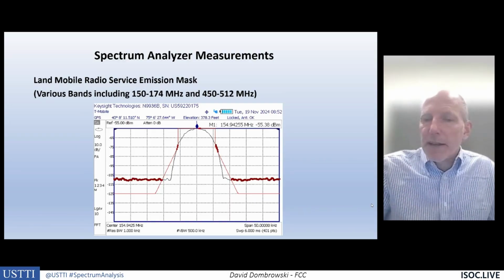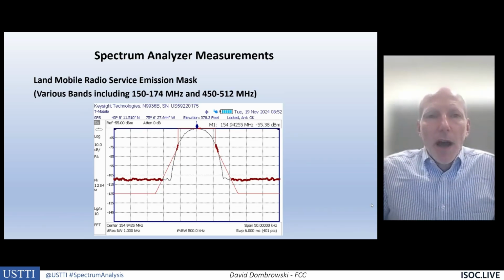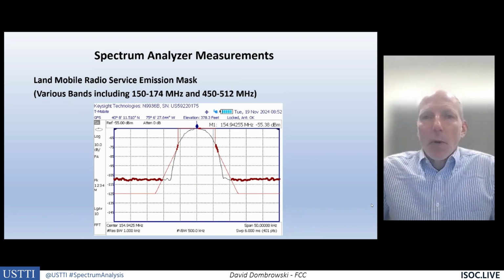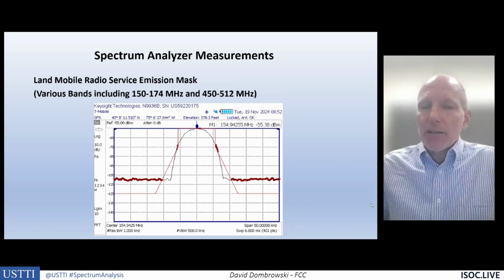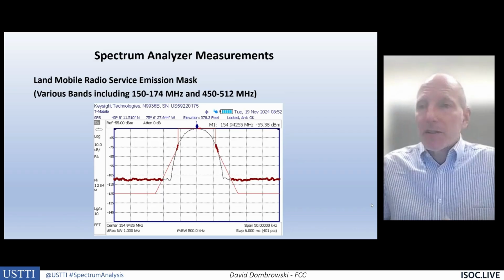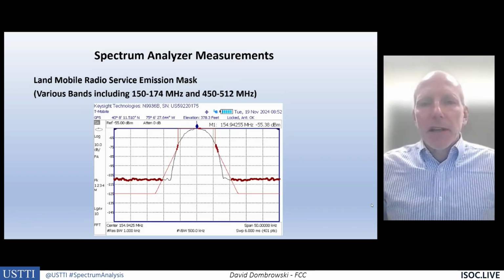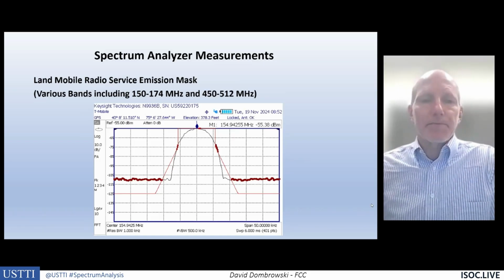And if you attended the interference presentation earlier this week, Shannon was talking a lot about interference, co-channel, and adjacent channel. And spurious emissions are very important. We have to attenuate those because those are the ones that we always find. The transmitter may be operating properly and still communicating properly, but now it's generating some of those spurious emissions outside the band and unknowingly causing interference to adjacent channel users.